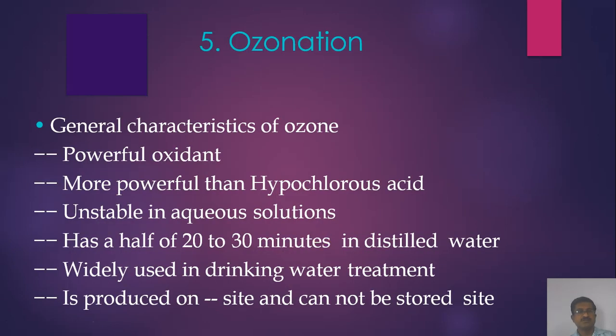Next one is ozonation. General characteristics of ozone: it is a powerful oxidant, more powerful than hypochlorous acid, unstable in aqueous solutions, has a half-life of 20 to 30 minutes in distilled water, widely used in drinking water treatment, is produced on site and cannot be stored on site. Remember, these are some points about ozonation.